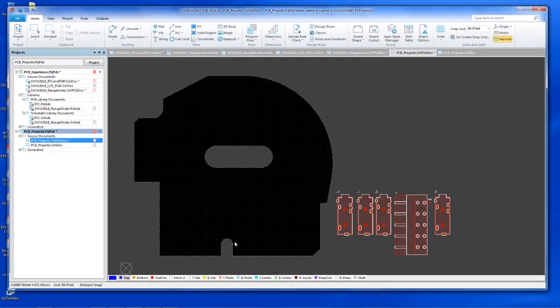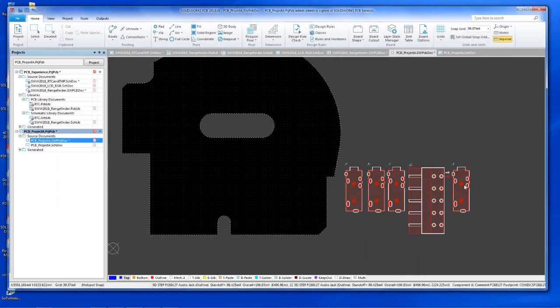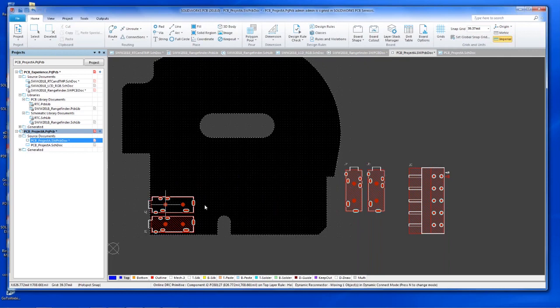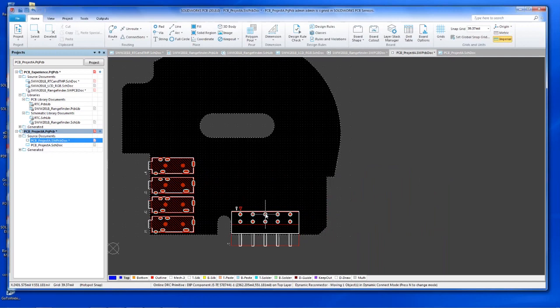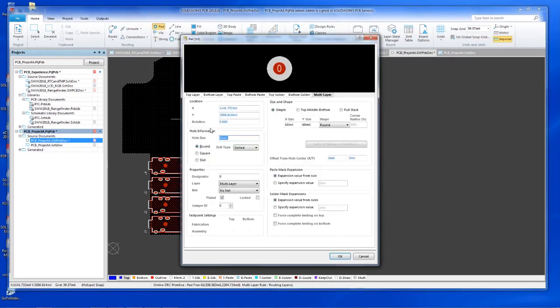Okay, so let's get these parts on the work surface and push this back to SolidWorks so that we can check the verification of placement and adjust if necessary. And there was that note to add 3 mounting holes. So on the Home tab, I would add pad. Okay. Check my pad parameters. Hole size needs to be 100.